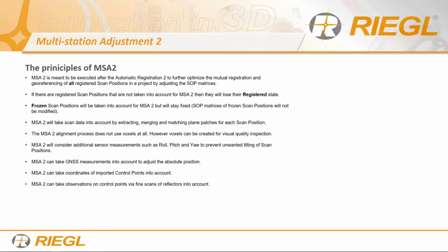This is cool too as well. So this is in a project scenario where you did a couple resections on a couple scans, and you tie it down to survey control, and those are your base points. You don't want those things to move. You can freeze them and still make use of the multi-station tool where you have other scans tied to it, right?